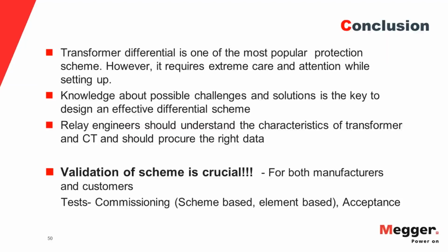Also, relay engineers should understand how a transformer works and how the CTs work. They should know the characteristics of both pieces of equipment in order to design an effective scheme. And of course, the validation of the scheme is crucial for both manufacturers and customers.